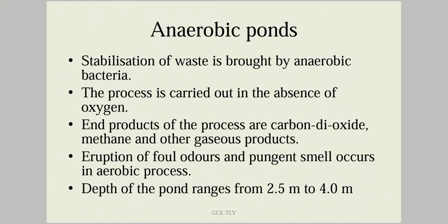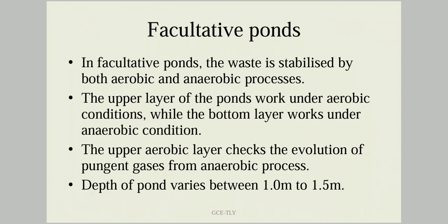Next, anaerobic ponds. In these ponds the treatment is brought about by anaerobic bacteria, and the process is carried out in the absence of oxygen. The end products are carbon dioxide, methane, and other gaseous products. Here there is a possibility of foul odors and pungent smells, since it is an anaerobic process. The depth of the pond is greater than that of aerobic ponds, ranging from 2.5 to 4 meters.